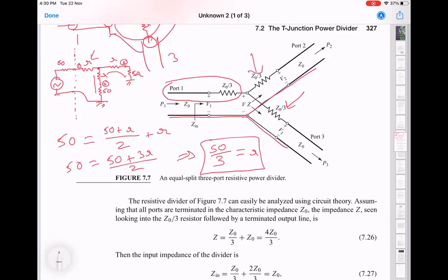I have something at the end of the transmission line. When I'm looking at Z0, I'm looking at an effective Z0. I consider everything at P1. There is nothing else. No, let's say if I have something. No. See, if you have something, then for that specific case, you can compute what the input impedance can be using the scattering matrix of the power divider, this one, and then applying the boundary conditions accordingly.